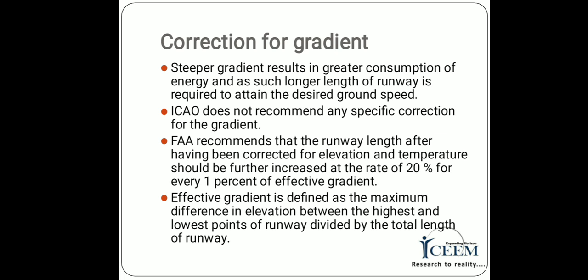FAA recommends that the runway length after having been corrected for elevation and temperature should be further increased at the rate of 20% for every 1% of effective gradient.